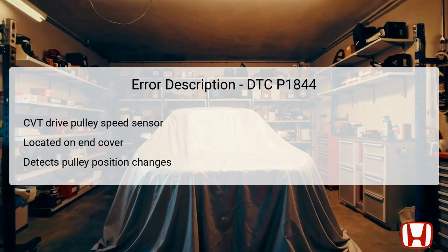The CVT drive pulley speed sensor is a crucial component of the transmission system that monitors the operational parameters of the continuously variable transmission. Situated on the end cover of the CVT, this sensor utilizes semiconductor technology to detect variations in the position of the drive pulley as it rotates. As the pulley turns, the sensor tracks changes in magnetic flux and translates these changes into pulsing electrical signals sent to the TCM.